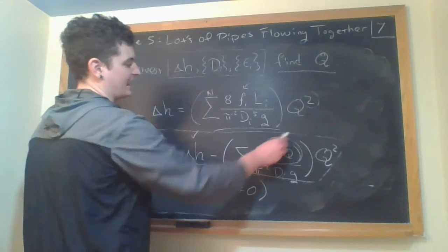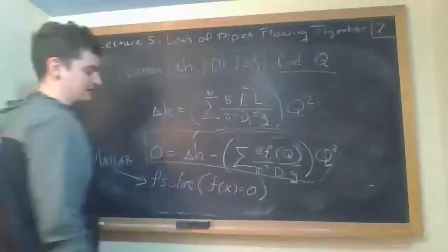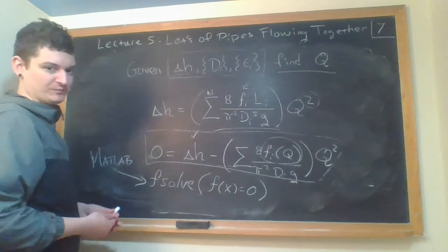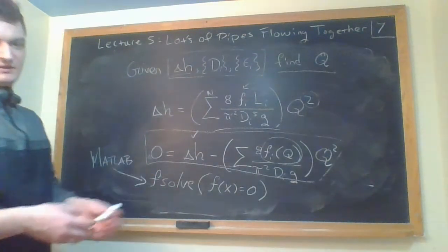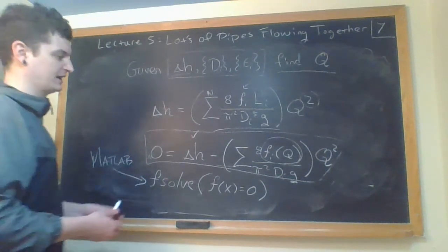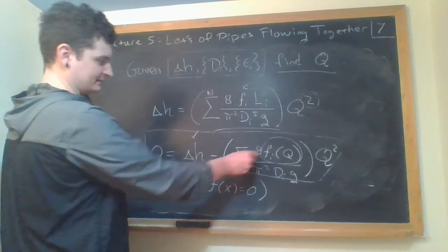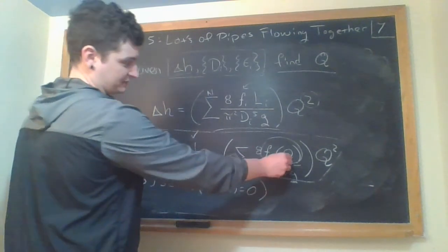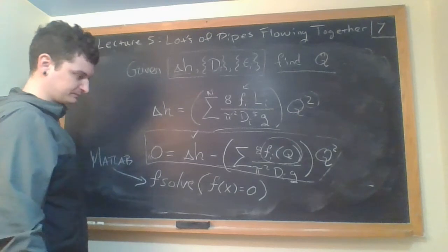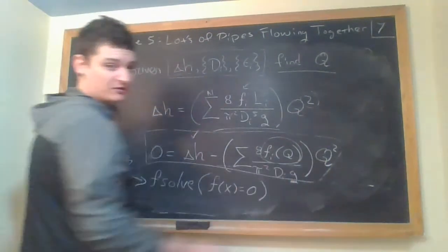How you write that function would involve, right? You need to implement how to make all the friction factors pan out here, because these are all equations themselves. But that's it. There's not really a difference between the pipe sizing problem and the flow rate problem, as long as you know what equation to plug into both of these things. So that's why I've written this many times. It's head loss, the 8, the function in terms of these Q flow rates, because you're never usually solving for a velocity. You're usually trying to solve for the flow rate.